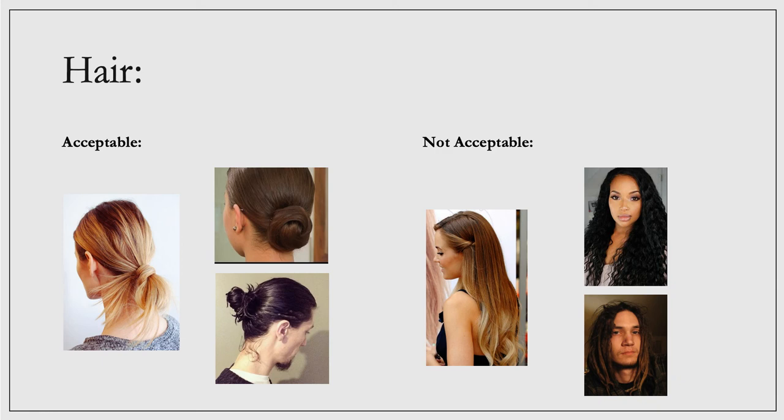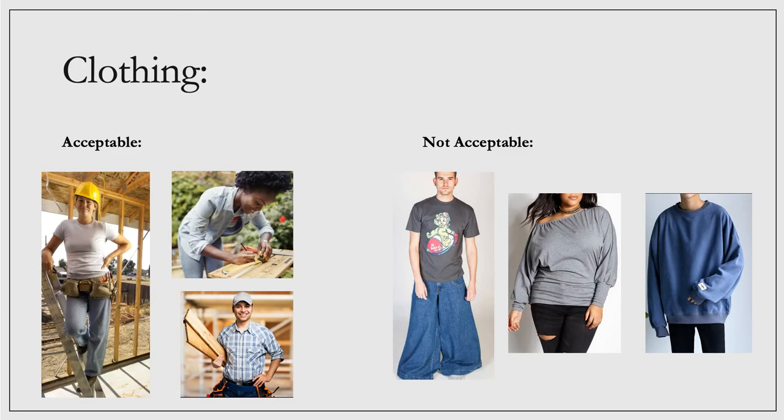Long hair is a beautiful thing, but in the scene shop, we do need to have it up in a bun or a ponytail that's nice and tucked up so that it cannot get caught in things like the table saw or the drill gun. And we all have our own individual fashion, but when you come into the scene shop to help construct the sets, you really do need to wear clothing that is appropriate, that is not too baggy, as baggy clothing will get caught in some of those tools and you don't want to experience that.